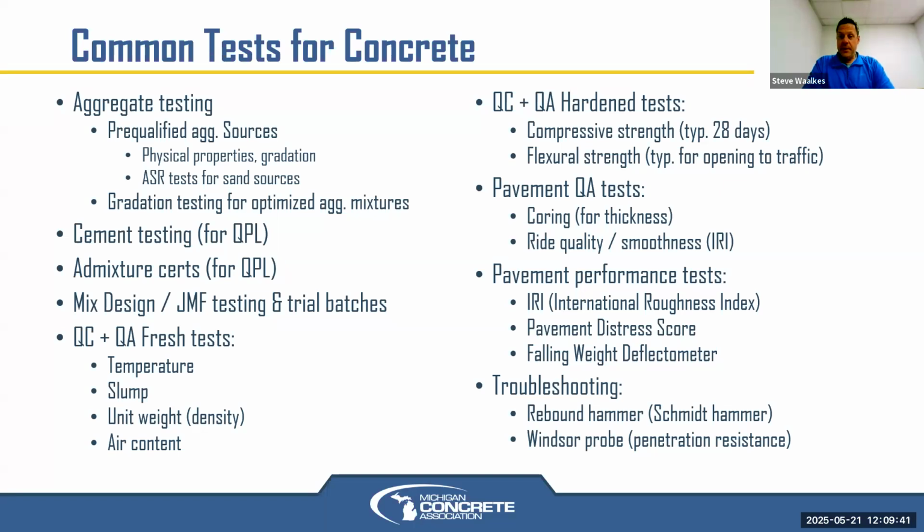As far as pavement specific tests, there are quality assurance or quality acceptance tests. Coring is typically done on concrete pavements for thickness to ensure that we have reached the design thickness in place.